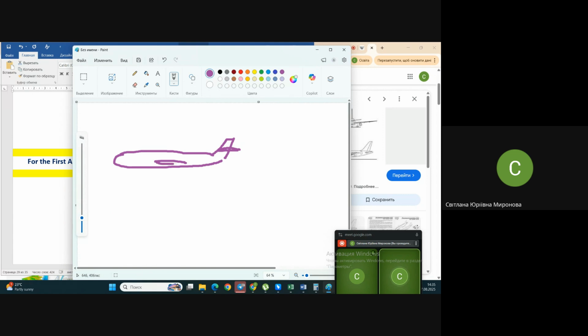When we have a wing, we have a stabilizer, and we have the so-called stable scheme. It means that we need to place the wing in such a way that the center of gravity, which we don't know where really, because it depends on a lot of factors, is in front of the position of the center of pressure of the wing. Not the center of pressure of the whole airplane at all, but of the wing.